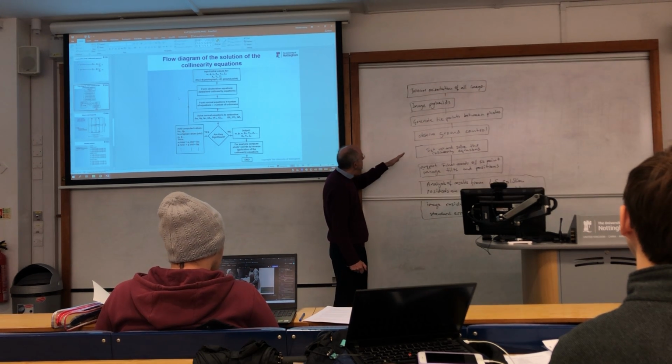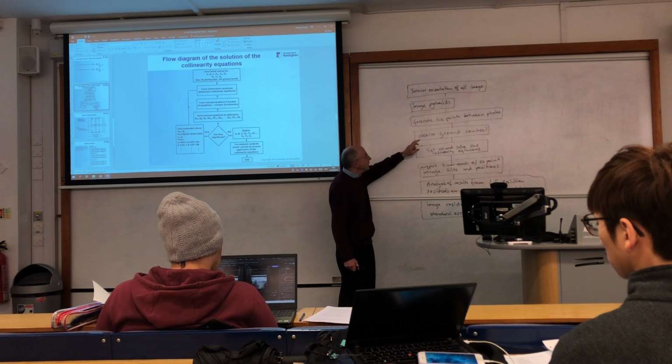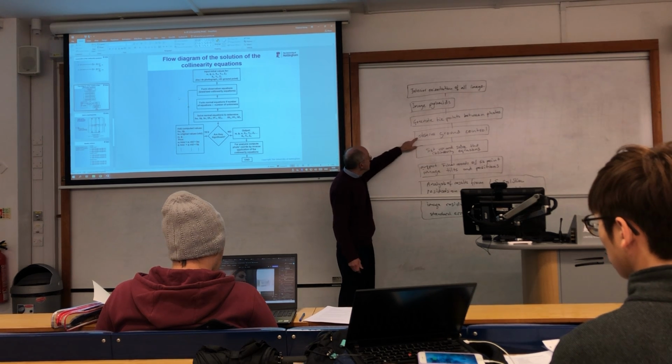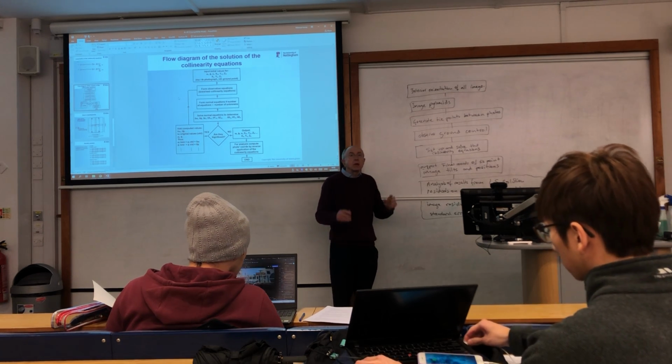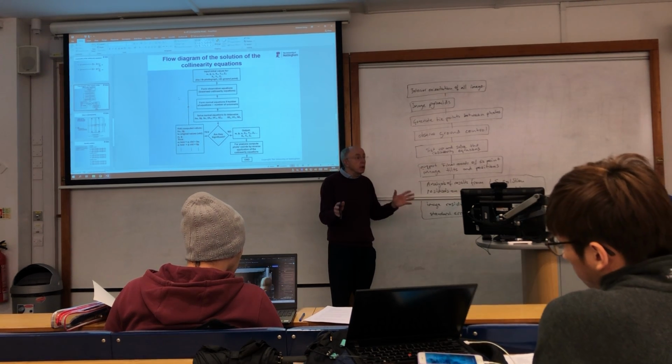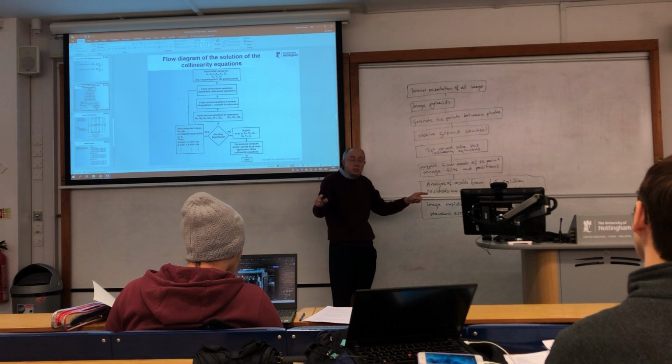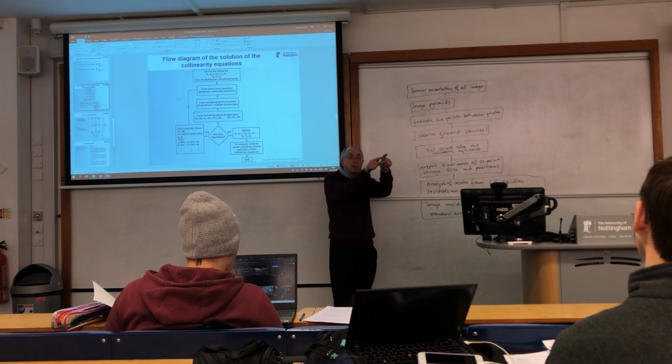If I was coming back to this, I've got a little bit of time. The other thing you could put in here on observed ground control is that the ground control is normally round the edges of the block, isn't it? And then we have checkpoints in the middle.